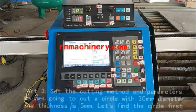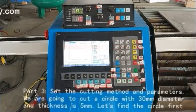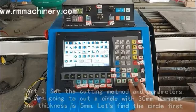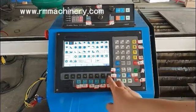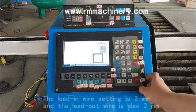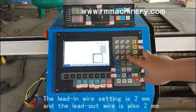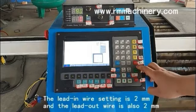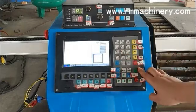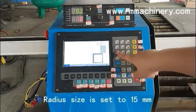Part 3, set the cutting method and parameters. We are going to cut a circle with 30 mm diameter and thickness is 5 mm. Let's find the circle first. The lead in wire setting is 2 mm and the lead out wire is also 2 mm. Radius size is set to 15 mm.